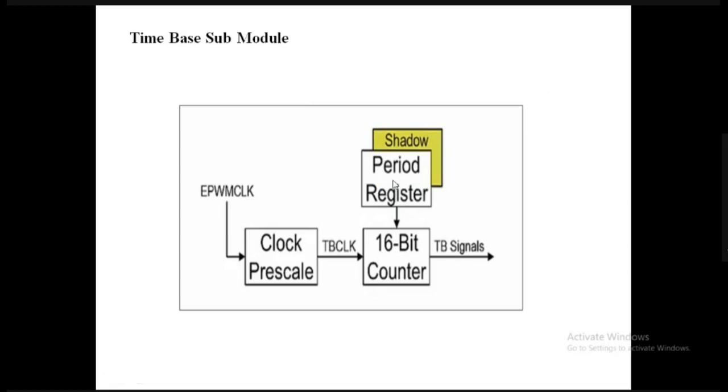You can take an example: if your CPU is executing instructions, and let's say some interrupt is called, and your microcontroller jumps to that address, then your microcontroller needs to remember the previous address, right? It needs to know which address to go back to in order to continue its execution after that interrupt. So it stores that location, from where it jumped to the interrupt, into a register generally called the program counter.